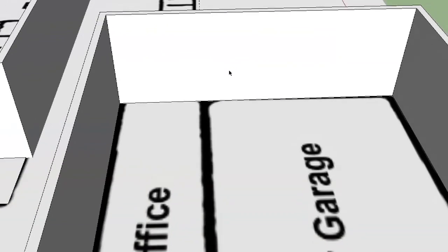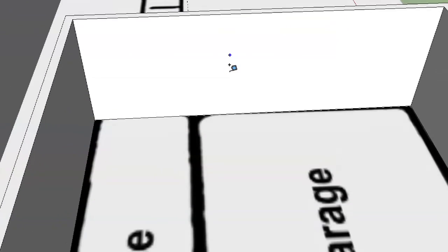So what I'm going to do is I'm actually going to use the guide tool, tape measure tool, and you can see even though I can't see that guideline, I can still snap to it. You can see it says online right there. So just kind of hover your cursor over the center until it snaps like that. And then we're going to click and drag out 3 inches to the right, another guideline, and then do the same thing to the left, like this. So now we've got those guidelines lining up exactly where we want our wall to be.